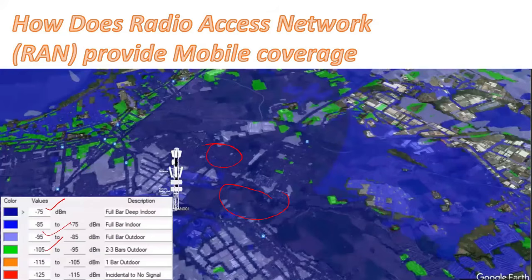So getting far away from the radio access network or cell site, our received signal level goes down, right? So this is the main principle. It is a combination of distance from the site and the path loss. So factors like obstruction in the area, where you are located, indoors or outdoors, population, and topography will affect the signal strength.